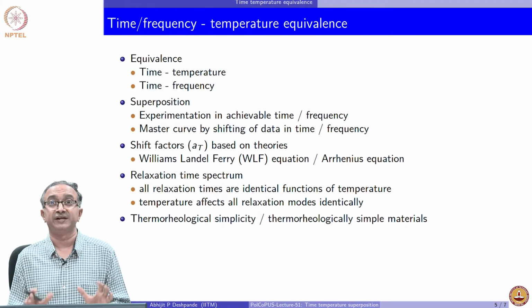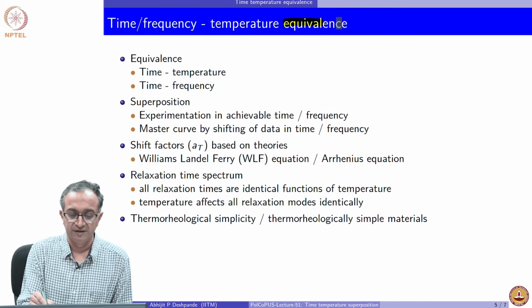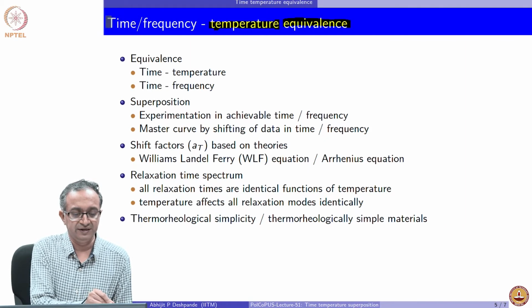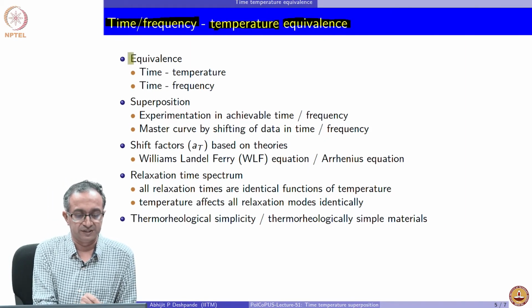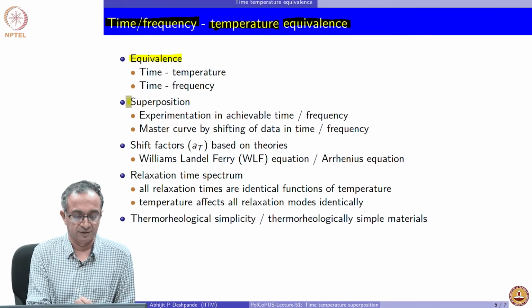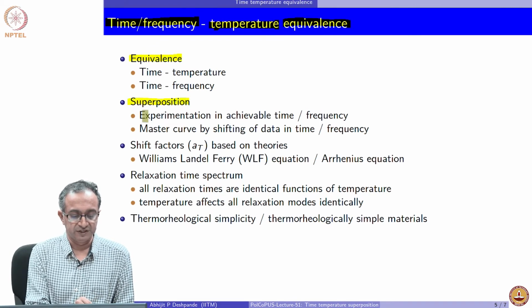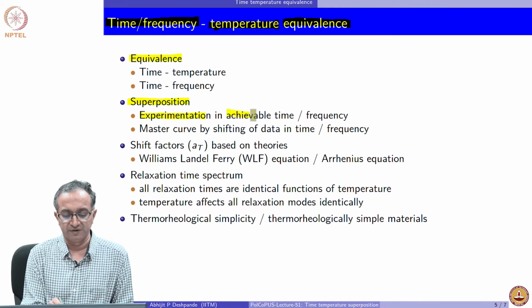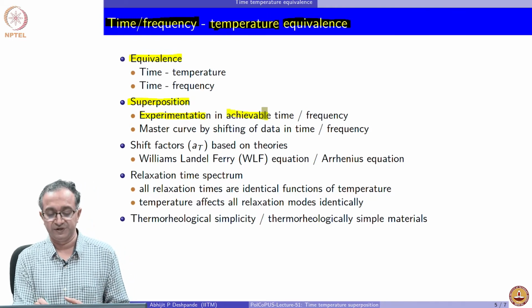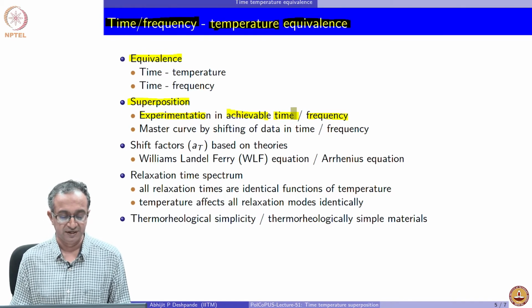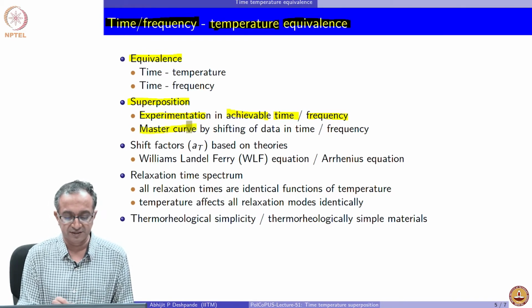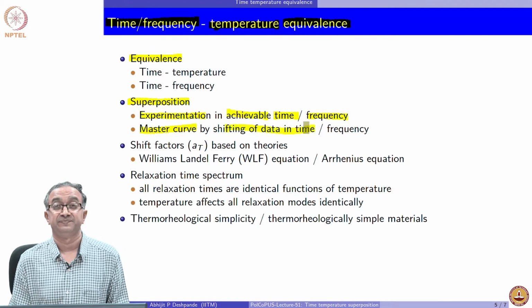So, generally what we are exploring is the equivalence between temperature on one hand and time and frequency on the other. And this equivalence lets us do superposition, in which what we do is we do experiments in whatever is the time that can be achieved or the frequency in which we can realize in the experimental conditions, and then we prepare a master curve by shifting of the data.